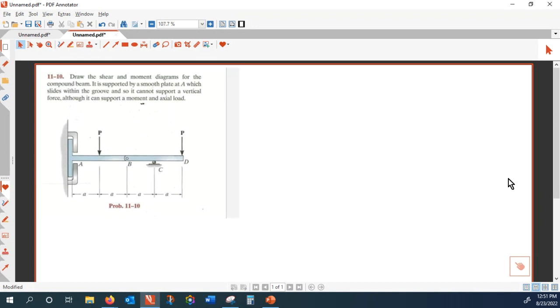What about, does it offer vertical resistance to vertical motion? Well, you see there are two gaps at the top and bottom. So that means this is free to move vertically, right? So I would classify this as a cantilever, but this is not a cantilever. Why is it not a cantilever? Because it does not resist against the vertical, and horizontally, we don't have any horizontal force.